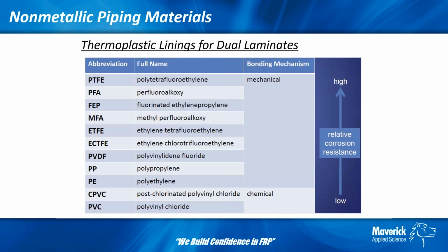When it gets to the steel, you're at a point where, if it's something so corrosive that you need a lining, once it gets to that carbon steel or even stainless, it's generally a matter of weeks before you see pinholes come through, and that pipe is toast. You're going to have to react pretty quickly at that point if you've compromised the liner.